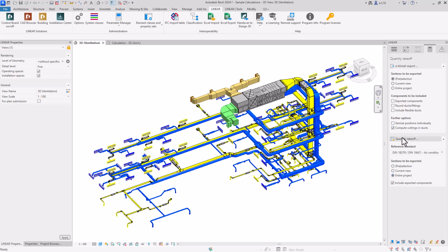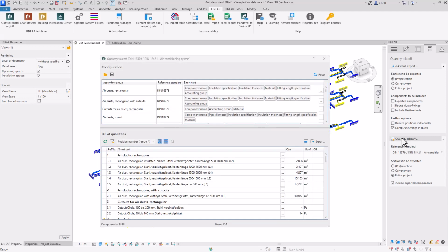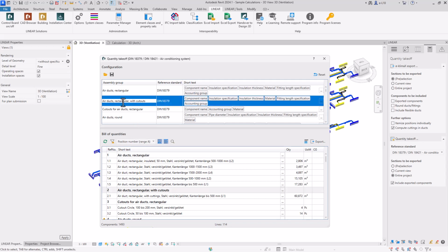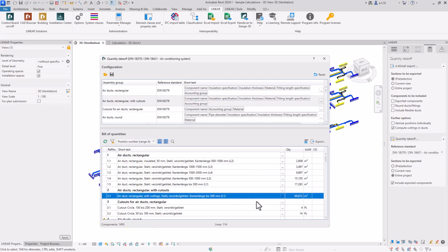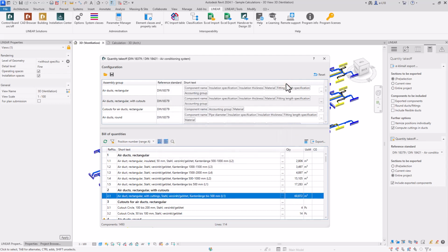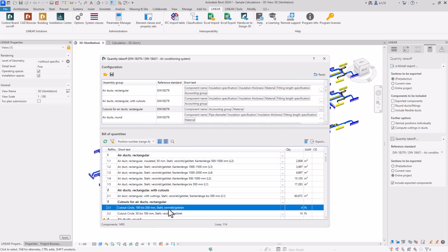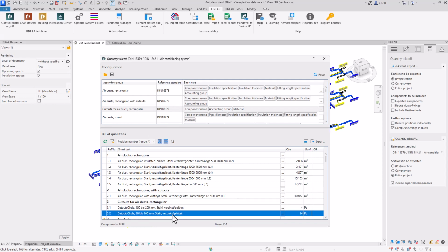However, a quantity takeoff of a ventilation system according to the tendering and contracting regulations goes far beyond counting database elements. There are many situations that cannot be modeled one-to-one or derived from a CAD model, such as overmeasuring recesses that are only produced after installation. In addition, the large number of component-dependent measurement and overmeasurement rules is another reason why model-based quantity takeoff is difficult to implement for ventilation systems.